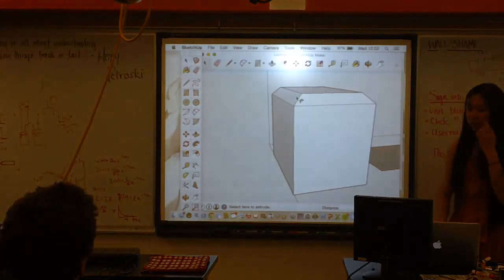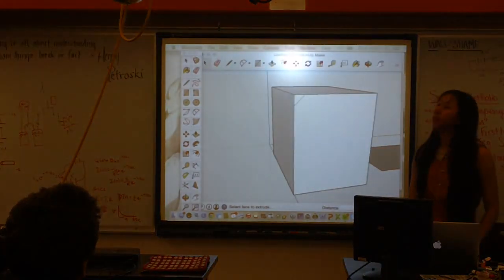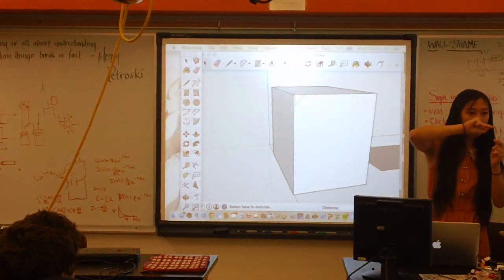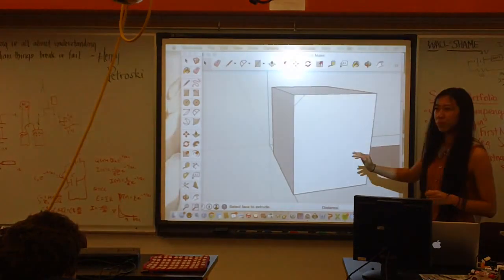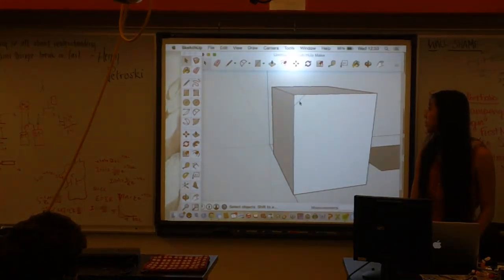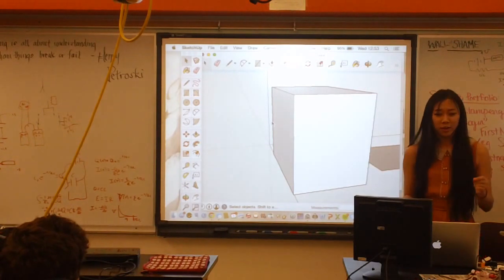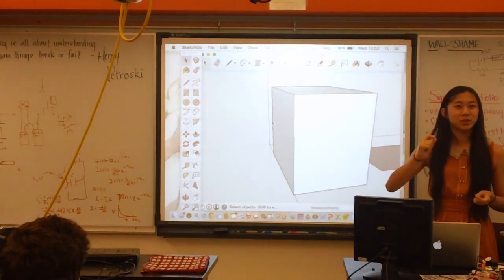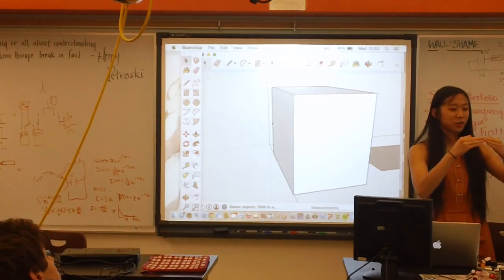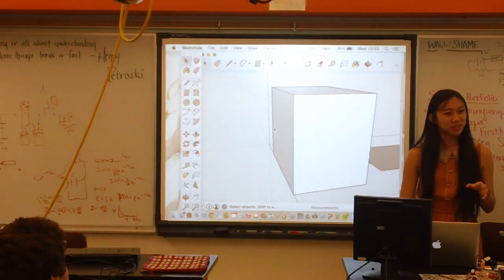Yeah, I can. The annoying thing about SketchUp is that sometimes when it makes curved lines, it's not actually one entity. A curved line in SketchUp can be a lot of really small straight lines. Since my dimensions are pretty small, actually they're not that small, maybe it'll work. What's happened to me before is that if the dimensions of my figure are too small, like an object just 1 inch by 1 inch, the resolution of the curved line isn't high enough, and then when you try to pull the object or use the Follow Me tool, it's not a closed object. So you get really weird shapes in space because it doesn't recognize what to do with it.